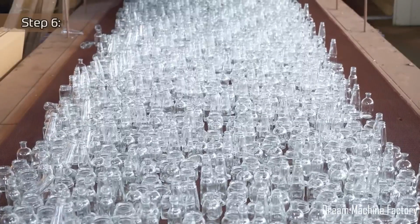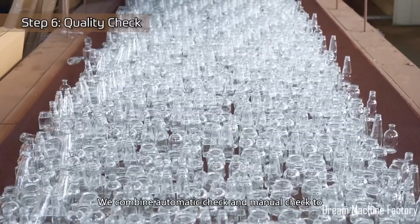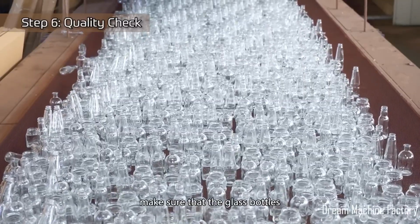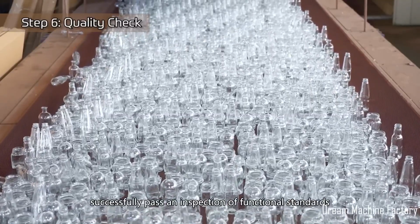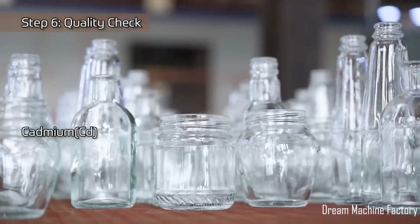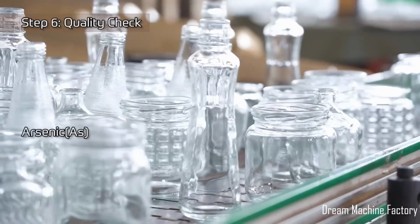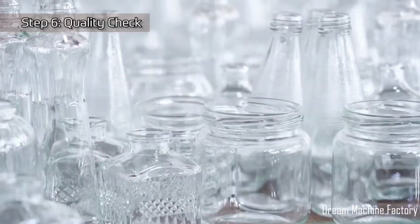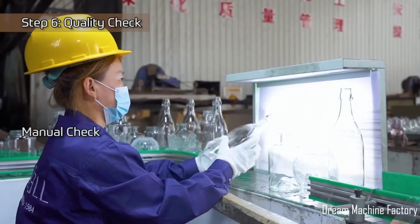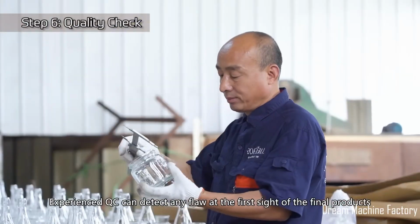In Step 6, every bottle undergoes rigorous inspection using automated detection systems and skilled visual checks. Defects such as cracks, bubbles, thin walls, deformation, or seams are identified. Faulty bottles are immediately removed from the production line, ensuring only structurally sound, visually flawless glass bottles proceed to surface treatment and packaging.